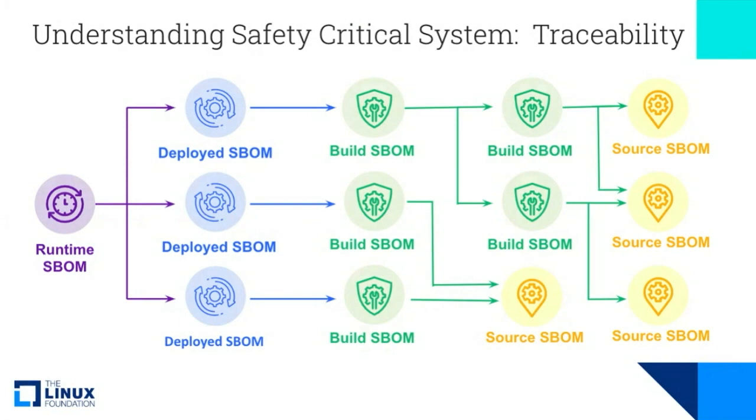If anyone's familiar with the Zephyr project, there's a one-line command you can add on, and every time you do a build, you'll get one build SBOM and 2 source SBOMs, and they're all linked. So you can see exactly what made it into your final image, your ELF image that gets downloaded onto some sort of sensor system. So it's possible today. We have proof of concepts out there. And it's just a matter of saying, yeah, we need to figure out how we can get this systematized a bit more.